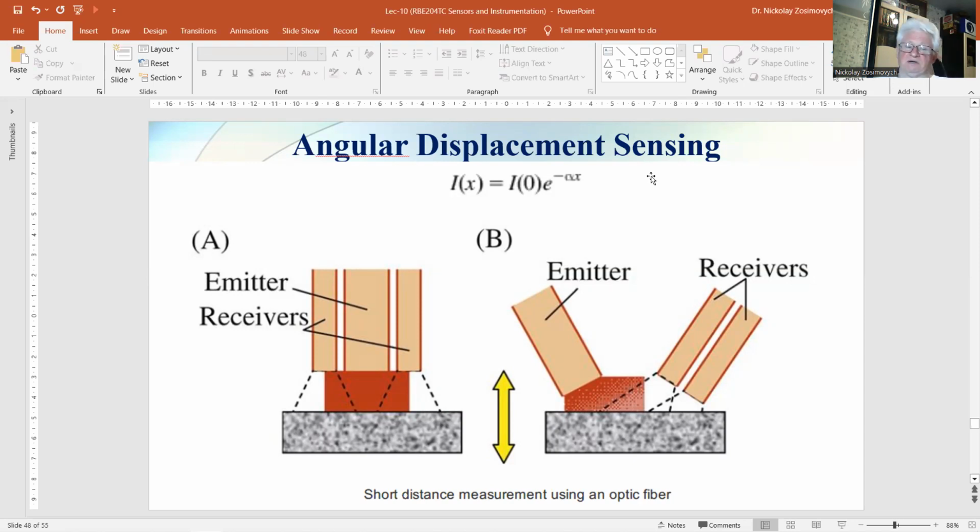The proximity sensor is also sensitive to angular displacement of the reflecting surface. This concept is further detailed: the fiber optic angular sensor is composed of a rotatable mirror, one central input fiber, and 4 output fibers. The configuration combines a high angular sensitivity and a negligible sensitivity to normal displacement.